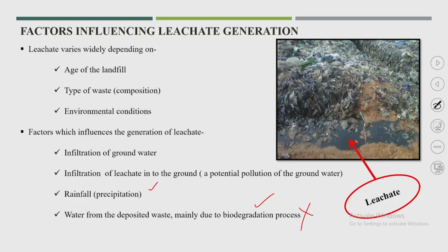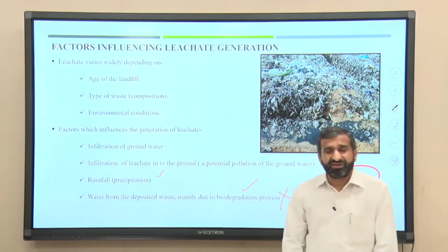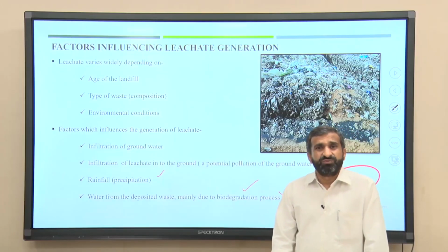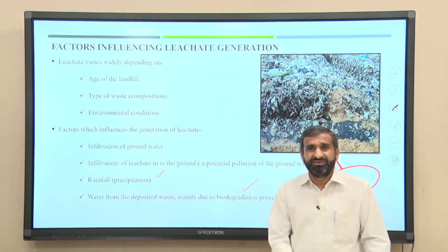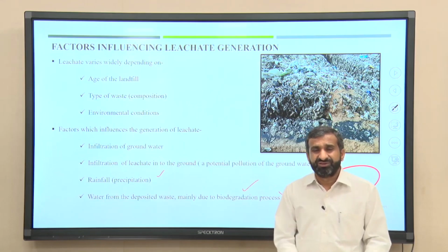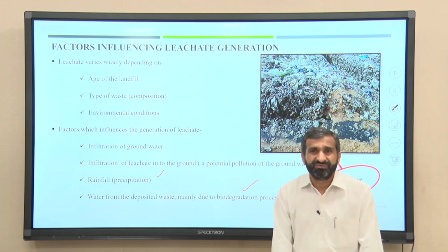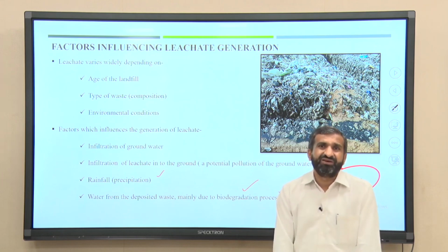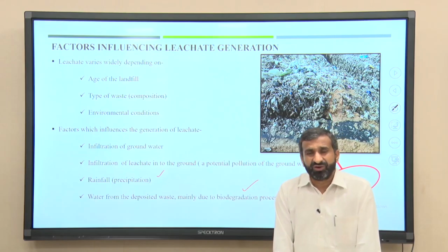Also, infiltration of groundwater needs to be checked; this is an important one. Wherever you finalize the location, try to find a location where the permeability of the soil is very poor, so that even if some leakage in the landfill is possible, the leachate won't reach the aquifer area or enter the groundwater.